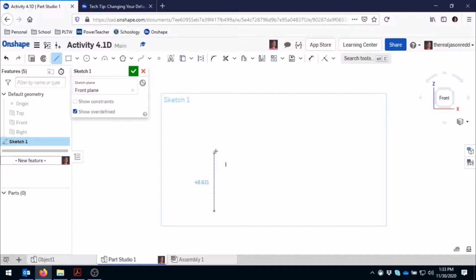So it tells me that this one leg here is a total of 40 millimeters high. So I'm just going to get it close. It doesn't have to be perfect right now. We'll fix that with a dimension tool. And I'm just going to draw this shape, and then I'm going to let the dimension tool get it exact. I'm not even sure how close I am to drawing this to the actual measurements. I'm not checking it.